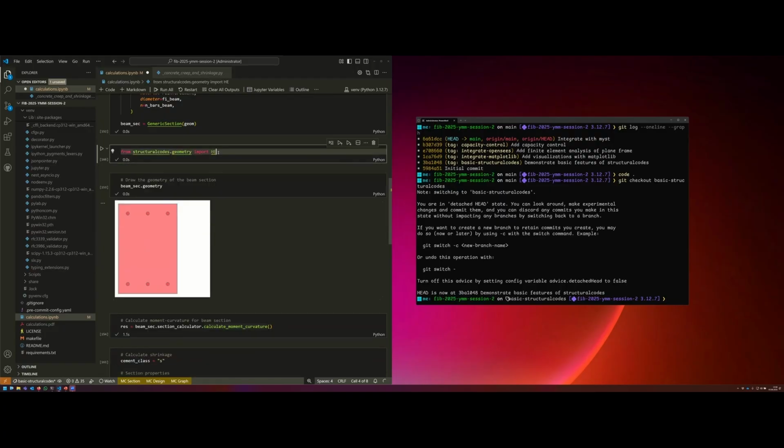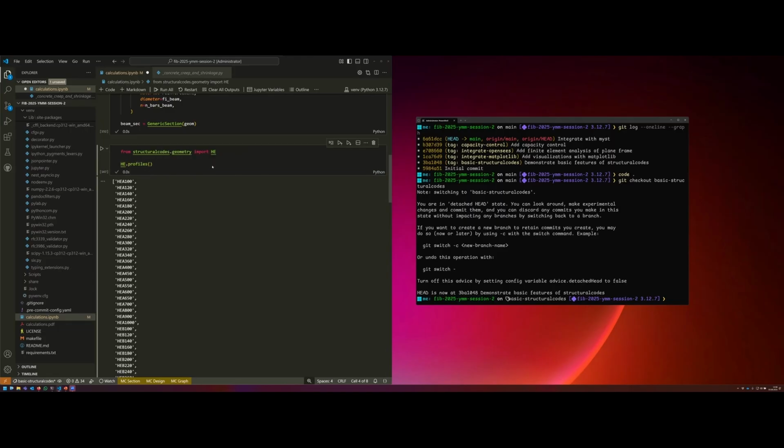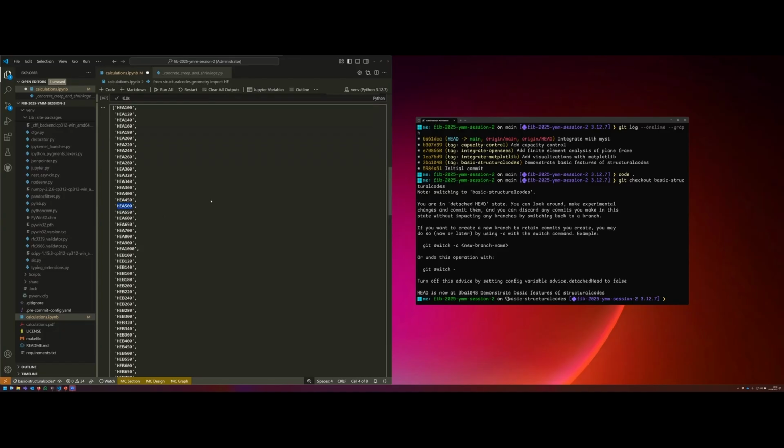So like this, we import HE, for example. So this is a HE, for example, A section. Now I'm talking about steel sections. So we can do he.profiles to list all the available profiles that we have in here. Let's see now. Let's do an HEA 500.